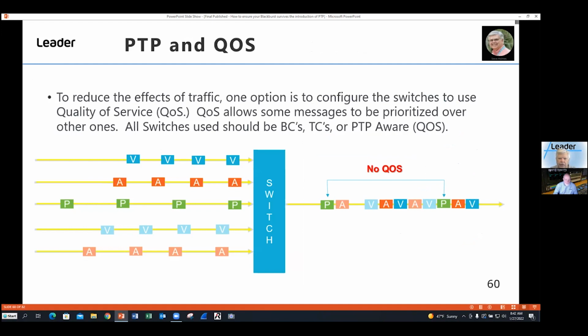You don't want to use QoS for the video or for the audio, because they are the main flows, and every packet then would be tried to be as the best packet possible. QoS needs to be set so only a specific flow that isn't necessarily the main flow through the switch would have the QoS on it. If you were to set the video or audio as QoS, you'd overload the CPU in the switch. So what you want to set for QoS is the most important thing, which in this case is PTP.